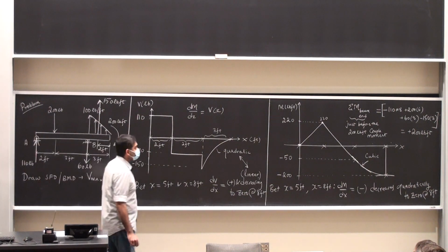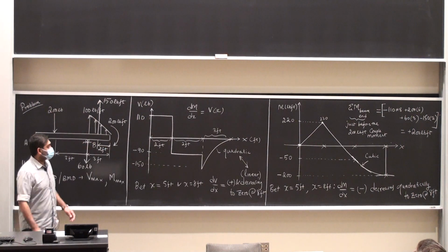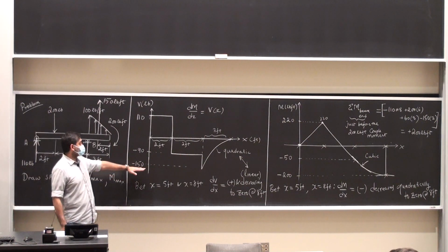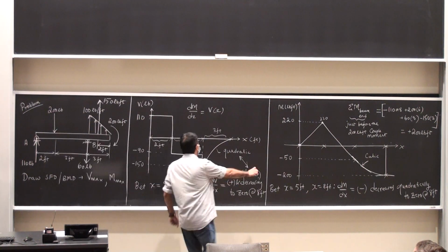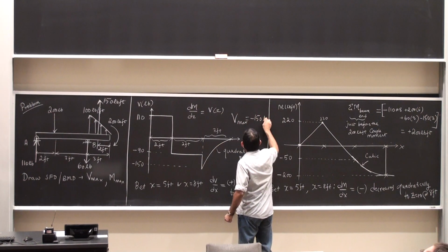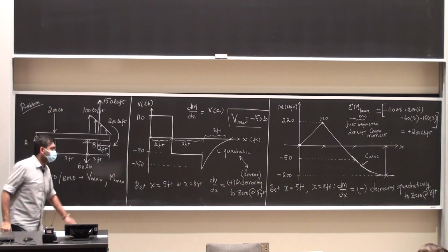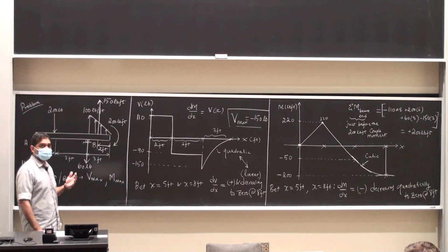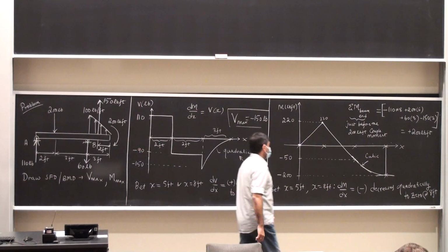Yeah. Okay. So what's the largest value of the shear force and what's the largest value of the bending moment? You've got to be careful here. The largest value of the shear force is 150 pounds with a negative sign. Okay, so V max is minus 150 pounds, and you're going to see the meaning of this negative sign. Essentially, it says that you're now in a direction opposite to the positive sign convention at that location. That's all it says.